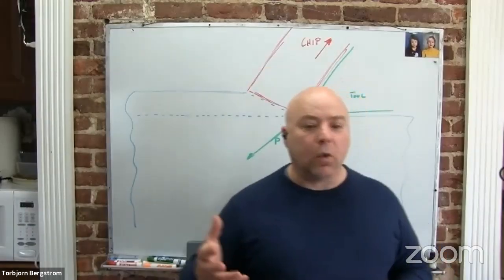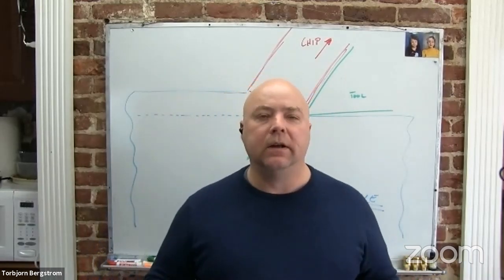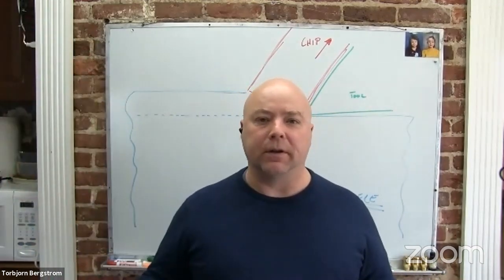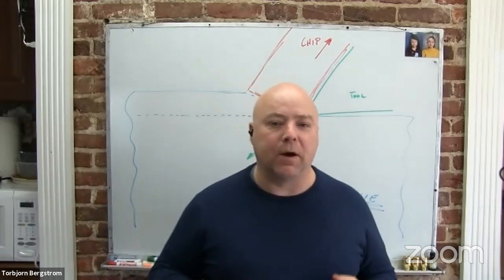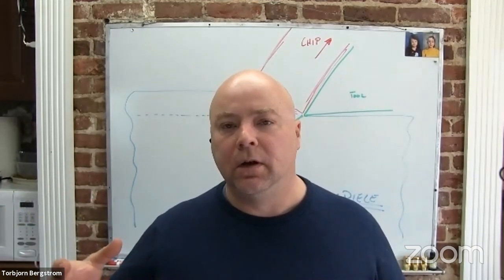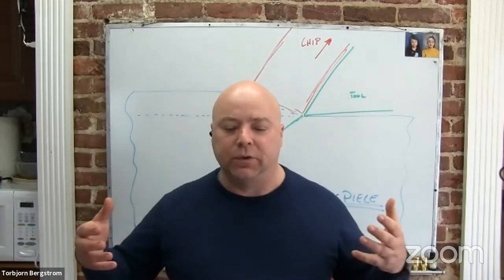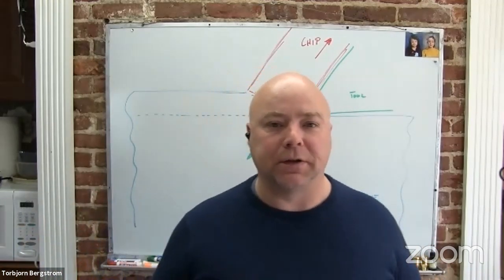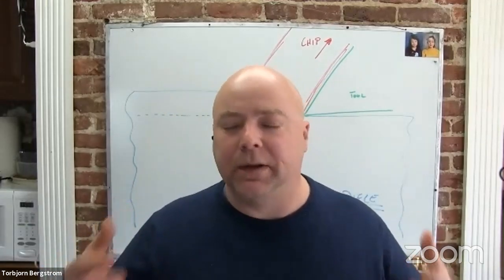I was going to say I'd probably want to measure it rather than estimate it because, for one, you'd be able to do so with things like a spindle load, if I recall. Okay, so one reason we might want to do it is if we want to optimize our ability to make the cut, and we know how much power. So this is not optimize as in reduce the amount of power that we use in total. This is optimize as in get the chips in the bucket as fast as possible and make the parts as fast as possible. And so if we can monitor the power, we can know how much power we have available. We could maximize our parameters. So our cutting parameters, those the PVs, the things we get to choose, we could maximize those to make the parts as fast as possible, if power was our limiting factor with our machine tool. So that would be one reason we might want to do that.